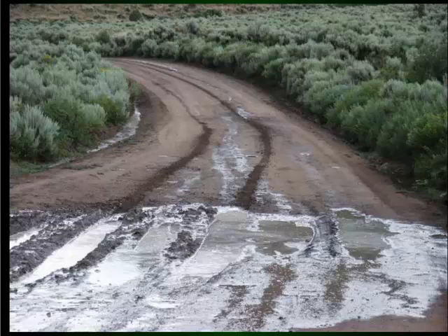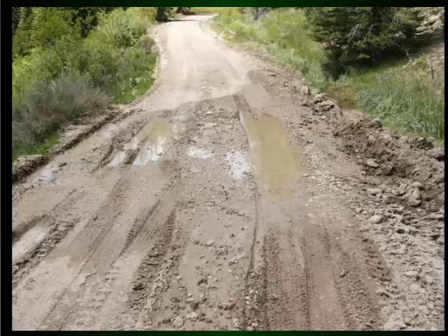Another example of a drainage issue, Red Creek Road. It's flat grade. There's no crown in this road at all. It's just flat across. And you get any kind of a depression, and you get this situation. You can see the difference between saturated and unsaturated. It doesn't take long, the saturation, the subgrade just starts disintegrating on you.